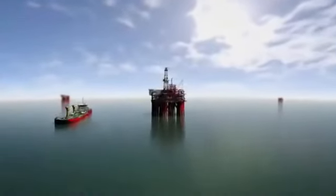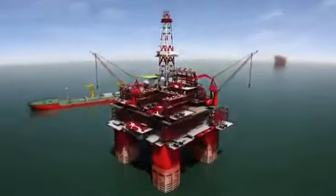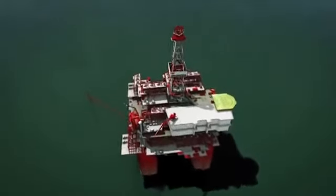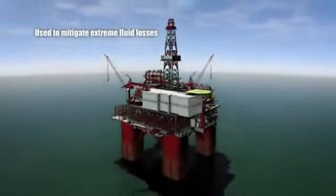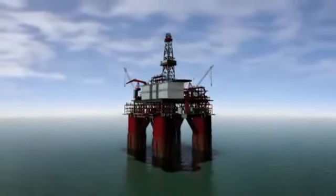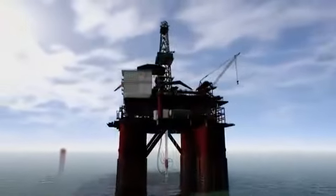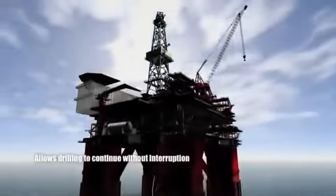Pressurized mudcap drilling is one of the 4 variations of managed pressure drilling, or MPD, recognized by the International Association of Drilling Contractors. Pressurized mudcap drilling is used to mitigate extreme fluid losses, commonly found in highly depleted and naturally fractured formations. In these extreme situations, where loss circulation techniques don't work or are too expensive, pressurized mudcap drilling allows drilling to continue without interruption.